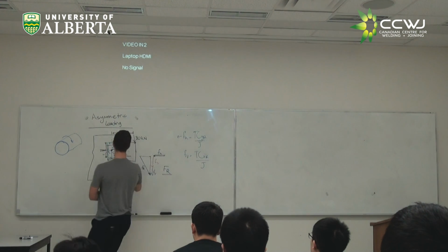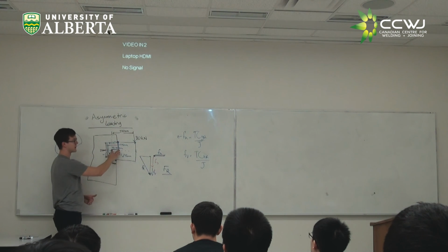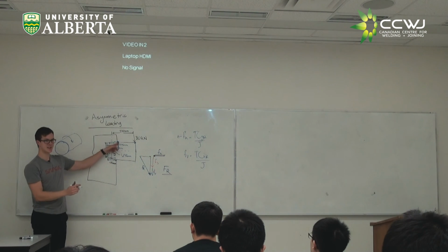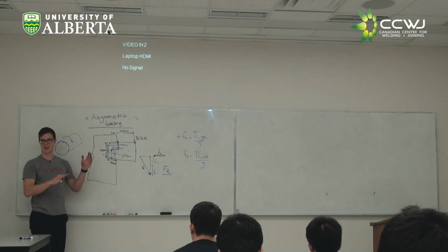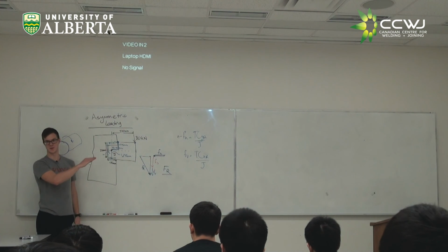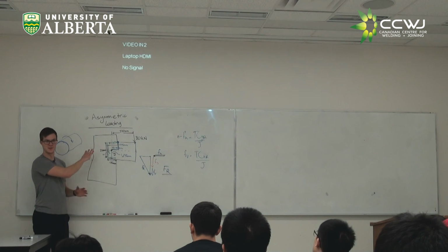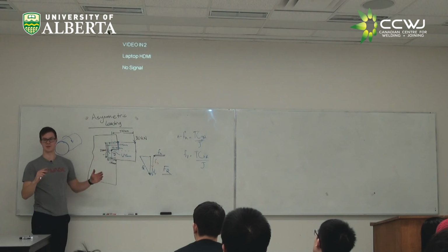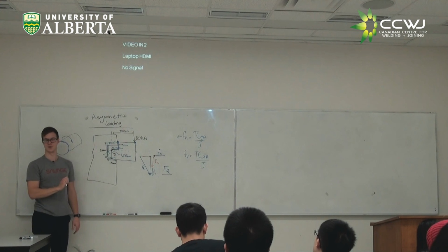So the CYR is our vertical distance from our center of gravity to our furthest point, and our CXR is our horizontal distance from our center of gravity to our furthest point. Now, another thing to note here, in this case, the point that's furthest vertically and horizontally is the same point. But you could imagine, depending on how crazy this weld looks, there might be a point that's furthest horizontally and a different point that's furthest vertically. So if you want to take the conservative approach, which is what the codes in this set of rules for solving this problem takes, you would have to choose those two different points. But it's just the vertical length to the furthest point vertically and the horizontal length to the furthest point horizontally.